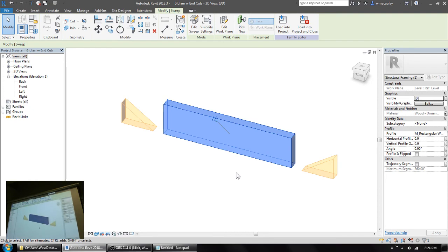But when we show it in plan, we show it open. So what we do is we can ask Revit to show geometry turned off in plan, making it invisible. Now, if we have a void and it's already here cutting a solid, you can't take a void and make it invisible. There's no functionality to do so. But what you can do is move the void away from the solid when you don't want it there, so you get the straight cut instead of the angled cut.